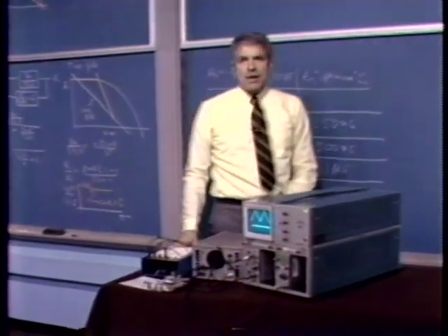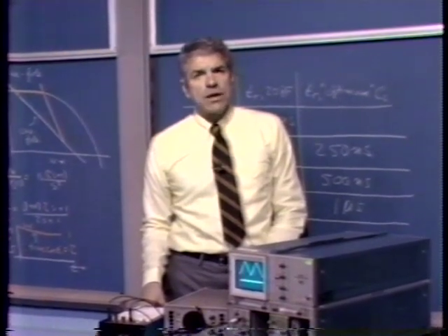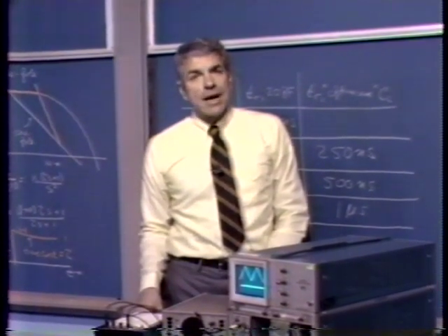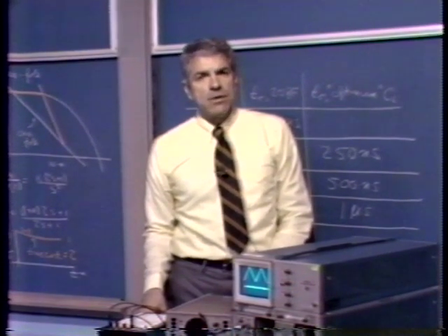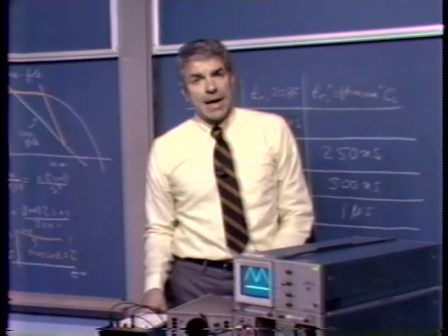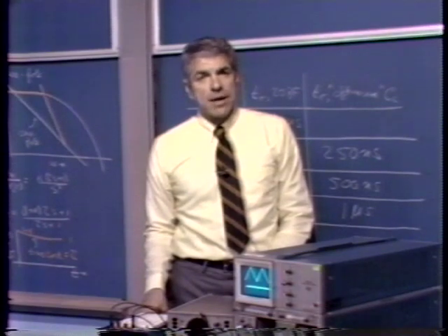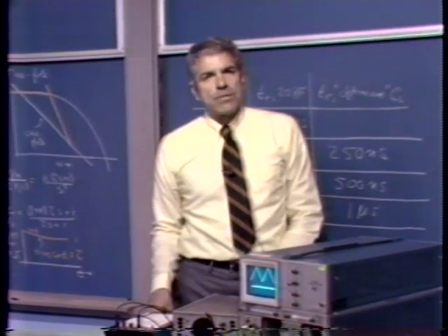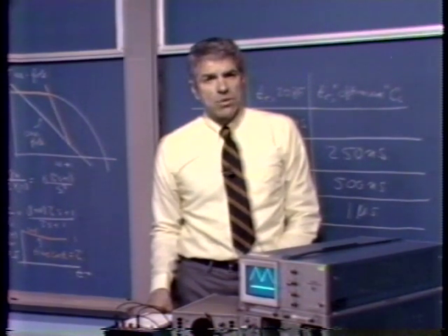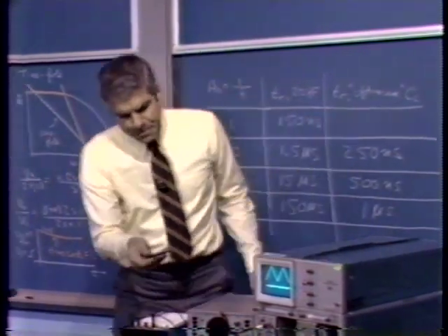Well, here we have changed the amplifier so that over a wide range of frequencies, its open loop transfer function falls off as 1 over S squared. In other words, over a wide range of frequencies, the output is the second integral of the error signal, or correspondingly, the error signal is the second derivative of the output signal. We have a series of ramps at the output, a triangle wave at the output. Why, we'd anticipate that the input signal would be the second derivative of the triangle wave, or a series of impulses. Of course, they're not perfect impulses. They don't go to infinity, reflecting the fact that we don't have a 1 over S squared transfer function at all frequencies. But we get a series of small impulses.